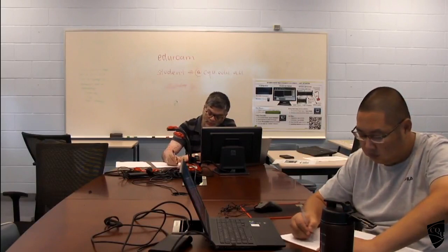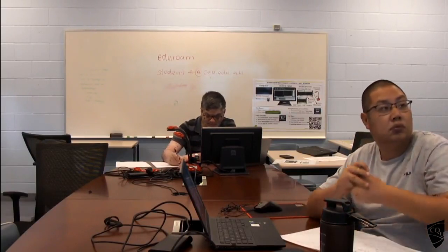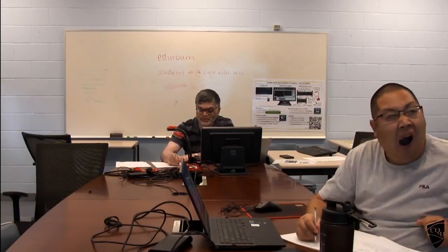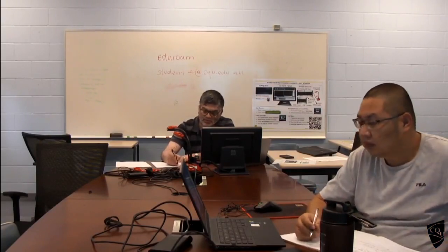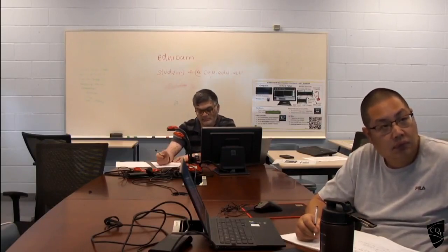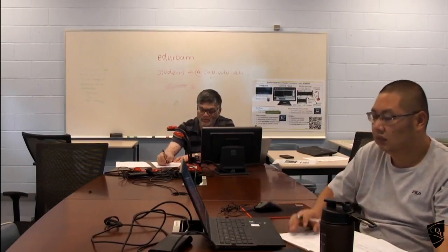In corner panels you can see we have two sides continuous, and here non-continuous, there's nothing here. So here no beams, sorry, no slabs. In the corner panels two adjacent sides are continuous, two sides are discontinuous. All the corner panels are like that.